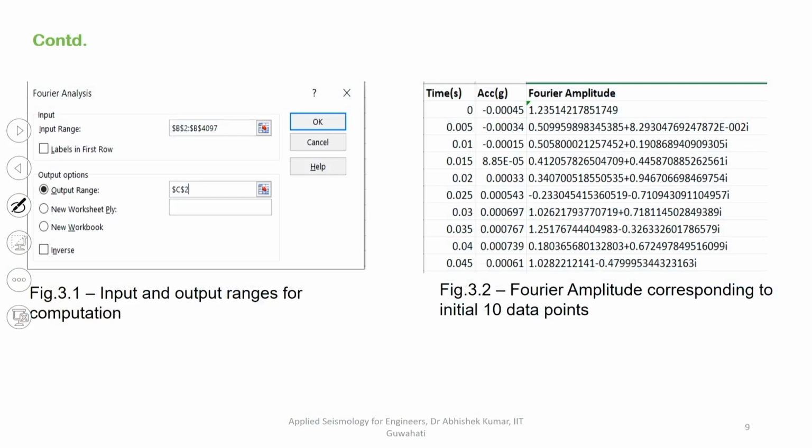So, in order to decide about the amplitude of motion, you will take into account the column where your ground motion record has acceleration versus time. Often you will be given the value of acceleration, the unit of that, and the time interval in which each value of acceleration has been recorded or sensed by the sensor.